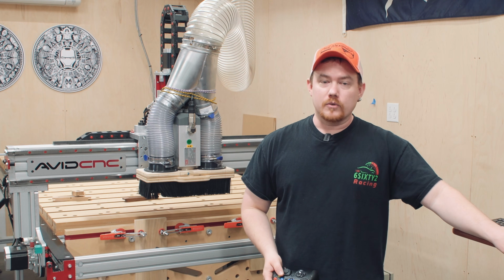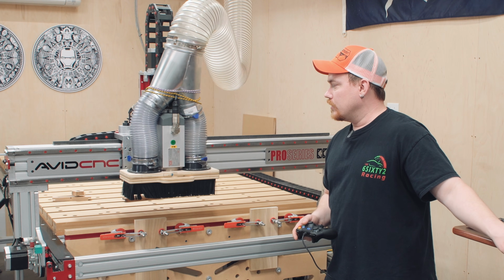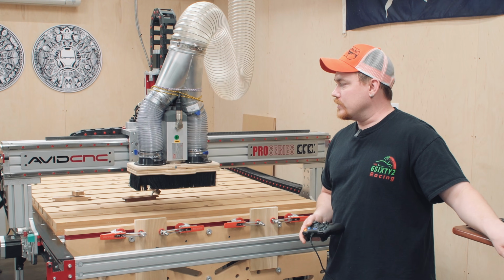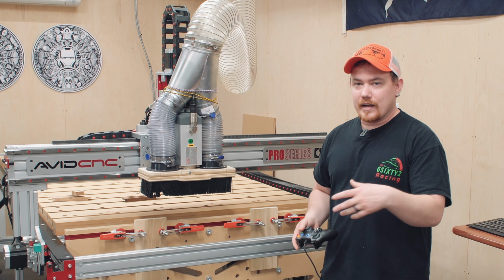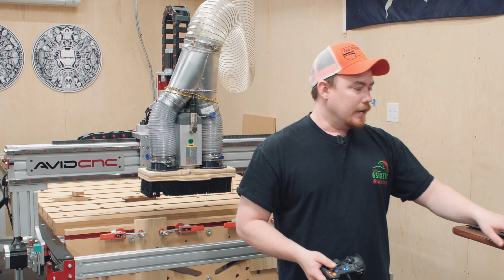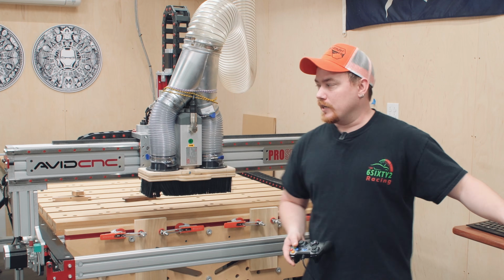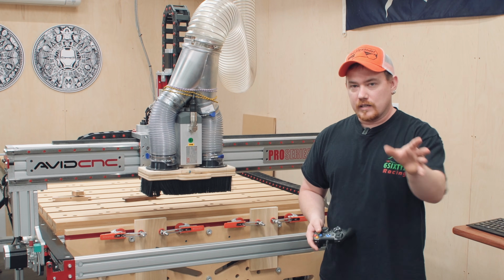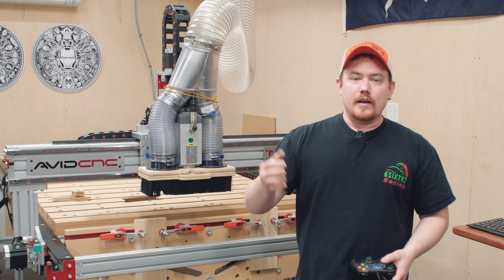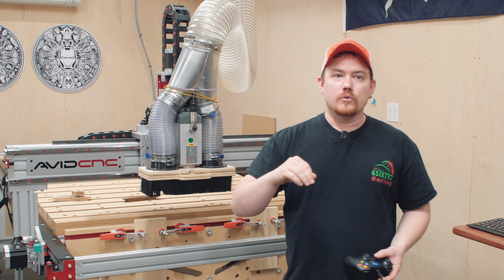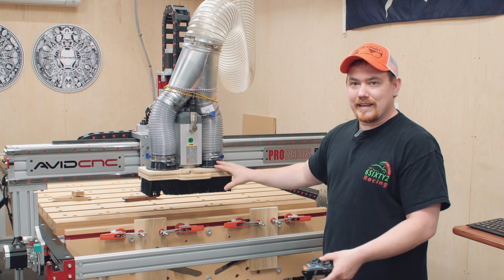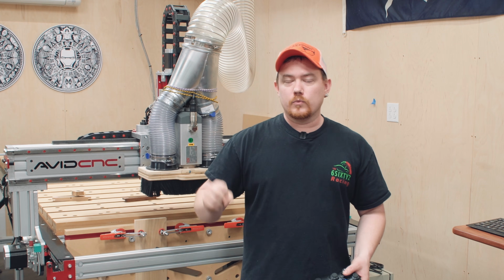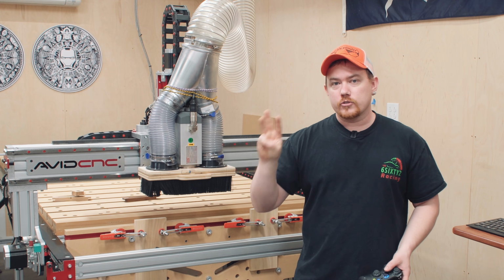So you have your directional arrows on the keyboard to move it left, right, up is a positive Y value, and down is a negative Y value. So that's your X and Y with the directional pad on the keyboard. Then also page up and page down is typically how you raise and lower the spindle. So page up, page down, and then the arrows. Now you can modify that. So there's 3 different ways to adjust that particular movement, and that's with no modification is number 1, with shift is number 2, and with control is number 3.